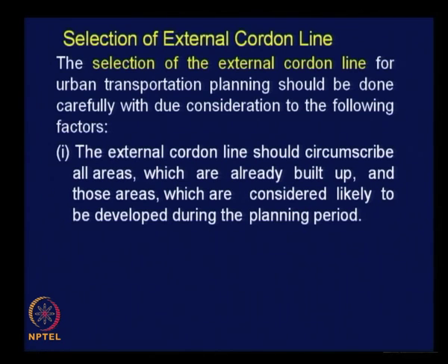What is the planning period? Yeah, it is the time gap between the base year and the horizon year. If you are fixing your horizon year to be 20th year, then planning period is 20 years, 2 decades, right. So, what is said here is that you should not just look at the present development alone, include all the areas which are likely to develop in the future during the planning period, right.